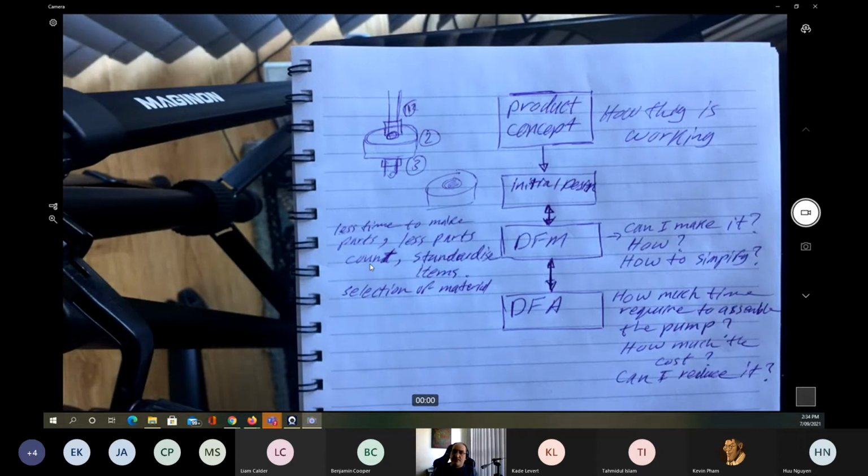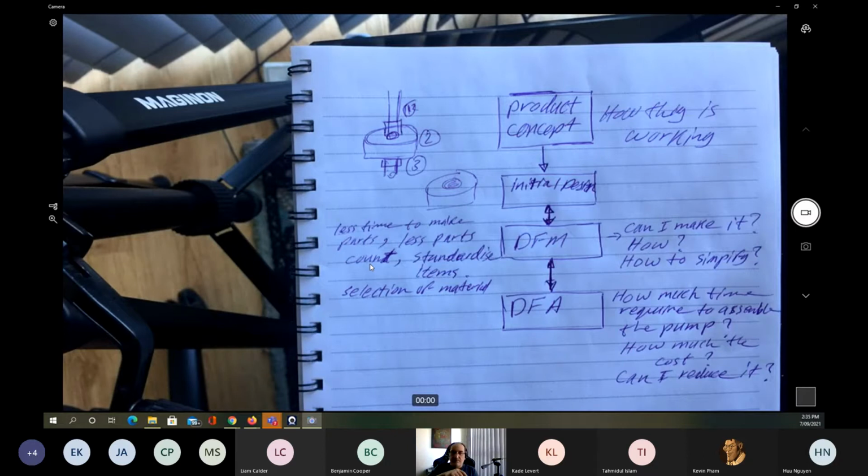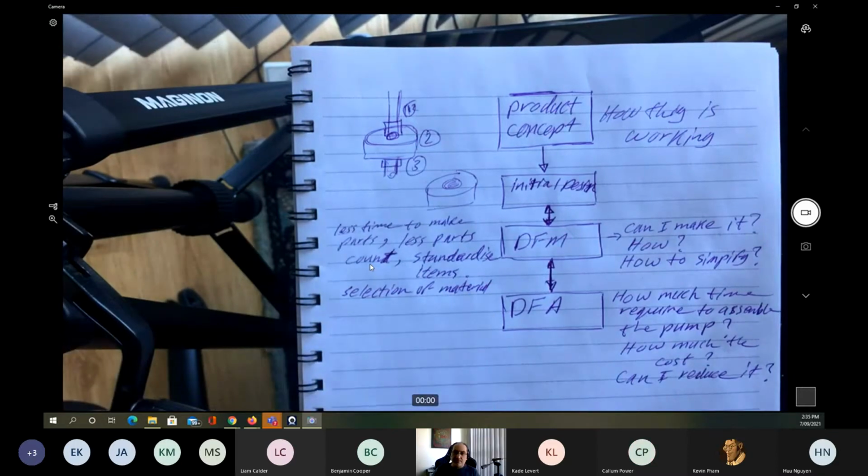And can I reduce it? Yes, I gave you one idea. The other ideas can always be available. For example, for the bottom valve, for the foot valve, actually, we're going to have the washer at the top, so you can glue it instead of having the nuts to hold the washer or the rubber washer. You can simply glue it on the valve, and it's going to be two parts together. The same thing is going to be happening for the foot valve.